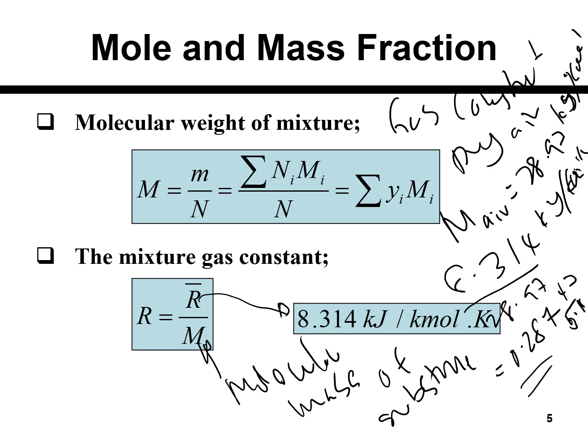If you want to calculate the gas constant for water vapor, the molecular mass for water, H2O, is about 18. So 8.314 divided by 18 gives you about 0.4619. If you want to calculate for a gas mixture, you can then determine the molecular mass for each substance.